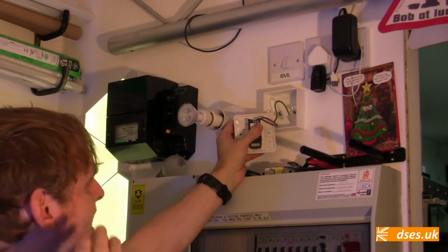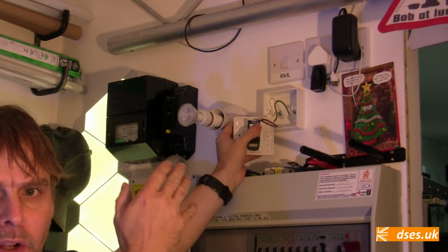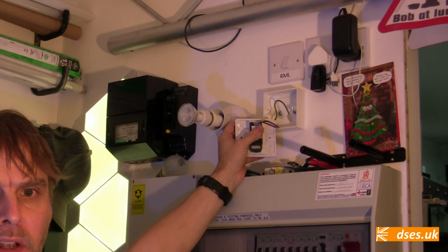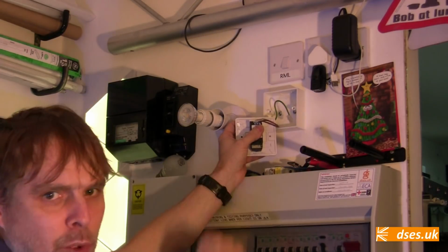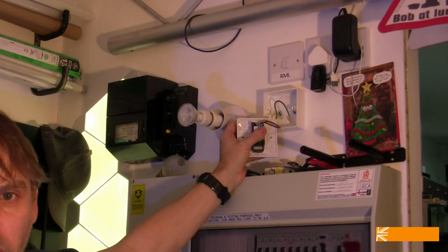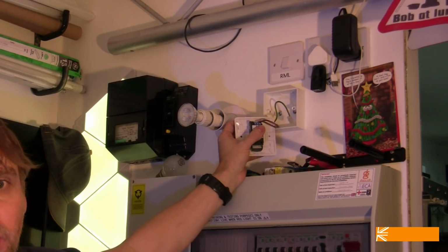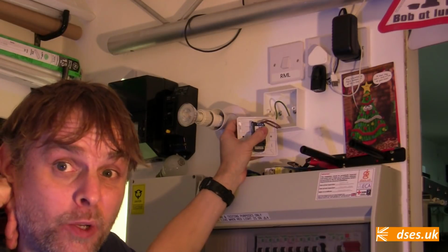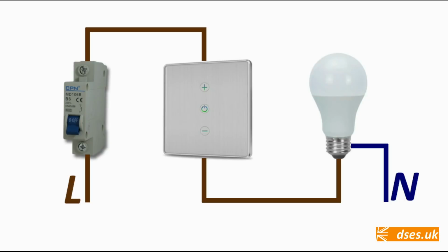So if there is a PCB in here and we've only got a permanent line in and a switch line out, then where does our clever chipset get its damn neutral from in order to power up, talk to your iPhone and set the moody light level when you cuddle up to your better half and select the Netflix and chill mode? If we break it down into a diagram, then we can see that the switch electronics does have access to neutral. It's just that it has to pass through one or more lamps to get there.